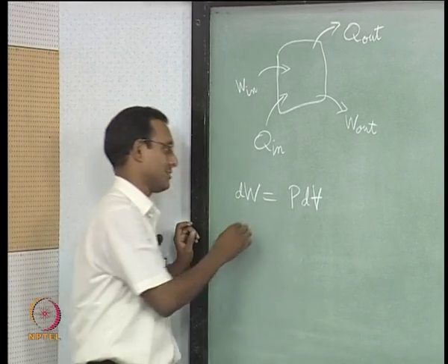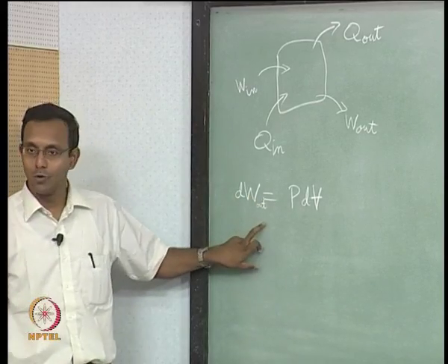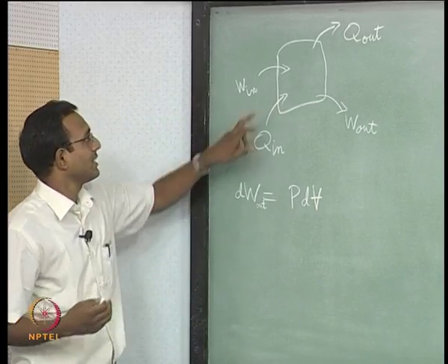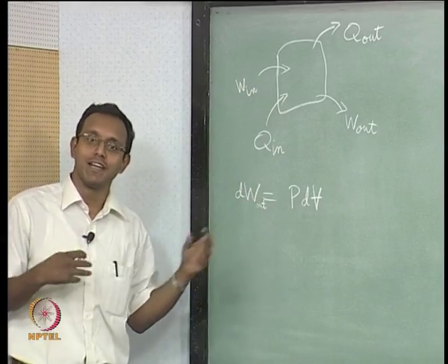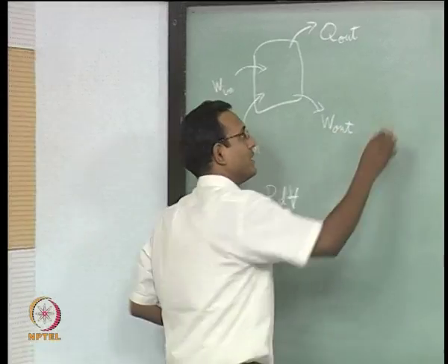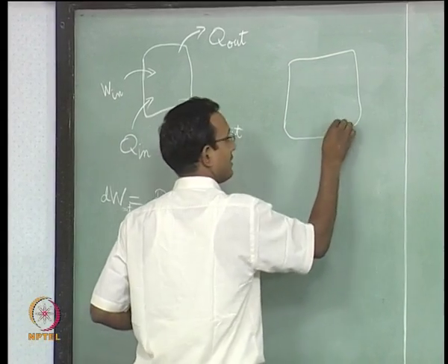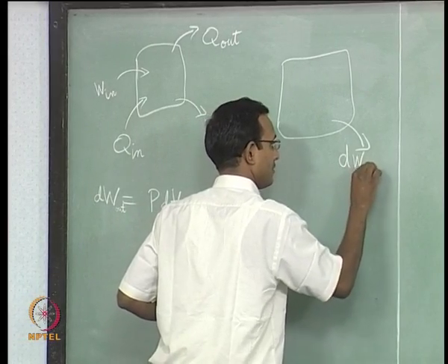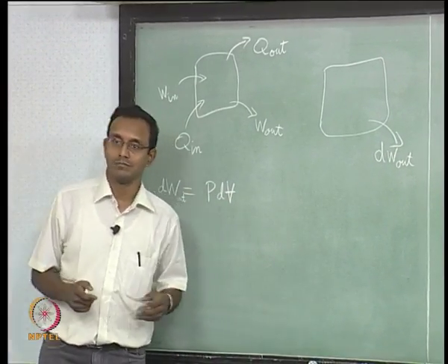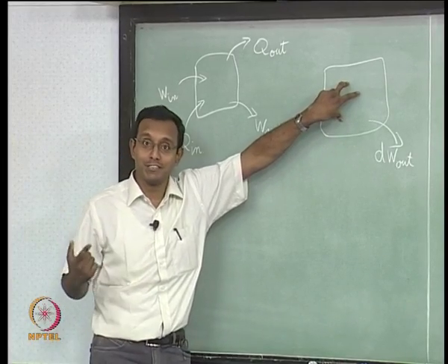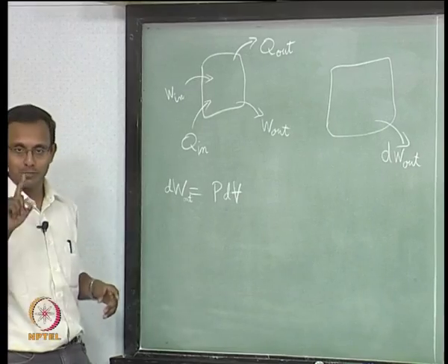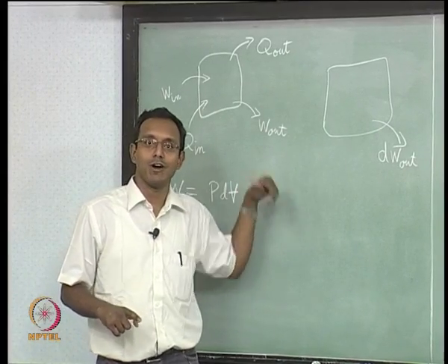We will consider this as W out. dW out is equal to P dV. We will just consider that way. So, now of course, I can consider a W in and a W out and then find out the net, or I will simply take the summation of all this and go to an equivalent system where there is net dW out, net work done outward. If overall the volume of the system decreased, I will automatically get this value to be negative. We will keep it that way. It just comes out to be negative, which means outside external surroundings are doing work on the system.